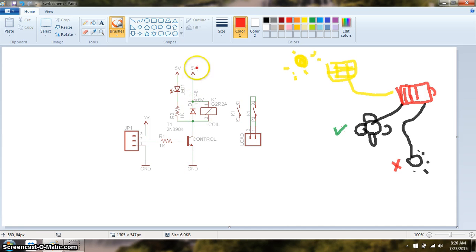What that means is that anytime this circuit is complete, I'm getting this coil charged, and when my coil is charged, at least in this circuit, it will pull off this switch, since it's one of those magnetic switches, and it will open this circuit. So this is the path. It's going to come down here, and the moment current tries to come back, it's going to bounce back from here.